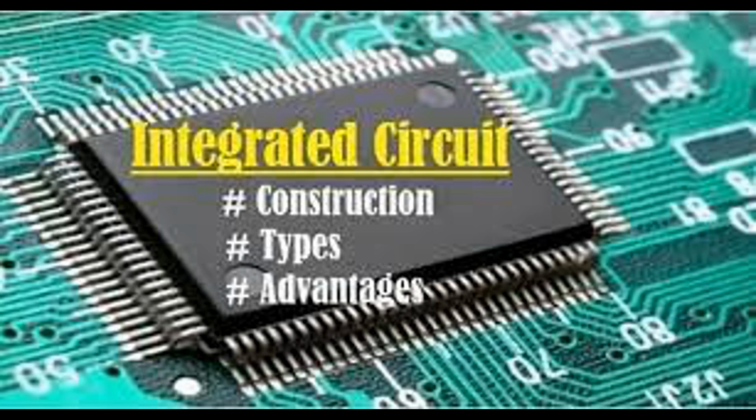The state of the memory elements at any given time is often referred to as the state of the sequential circuit. Clock signals. Sequential logic circuits are often controlled by a clock signal, which provides timing for the operation of the circuit. The clock signal determines when the memory elements should read and store data, and when the stored data should be updated.